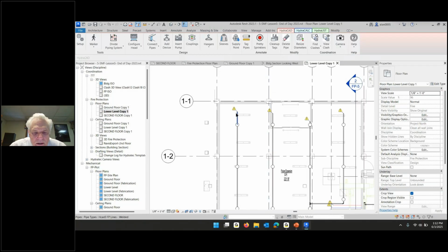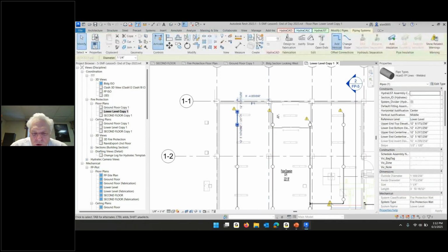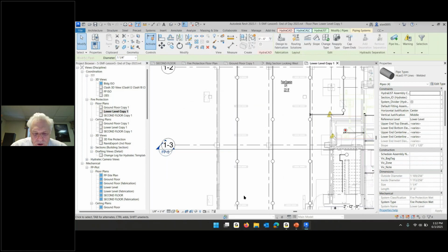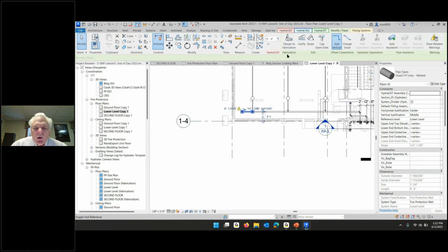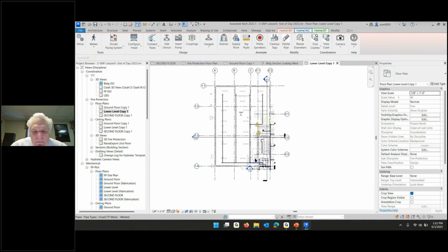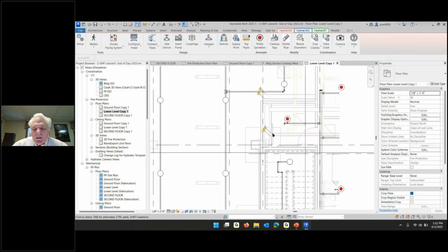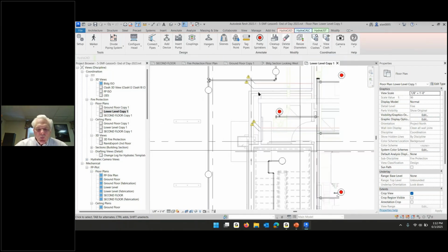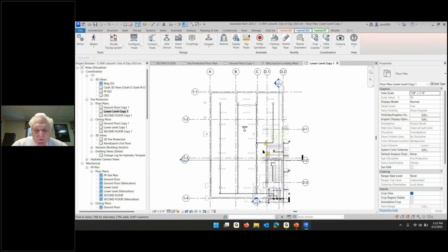And then I'm going to take that pipe, control that pipe, control that pipe, and control that pipe, and say add 6 inches or make it 6 inches and put a cap, and then I'll go 6 inches and a cap on that guy. And these little darts are concerning, but if you look closely, that's the copper tube that's not connected. That's the plumber's problem, not mine. So I'm not going to be upset about it.